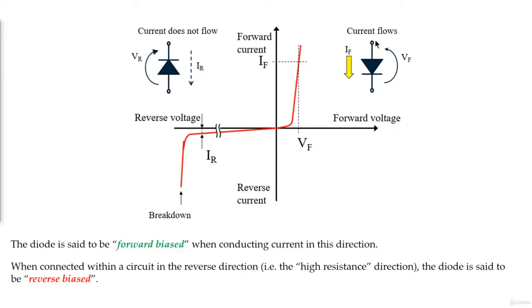So diodes begin conducting current only if the voltage across its two legs is equal to a certain voltage, also called the threshold voltage. So as you can see here, when the forward voltage drop across the diode is very close to this Vf, which is the threshold voltage, the diode suddenly starts conducting current through it. Of course, not very suddenly, but it's true that it's increasing very fast.